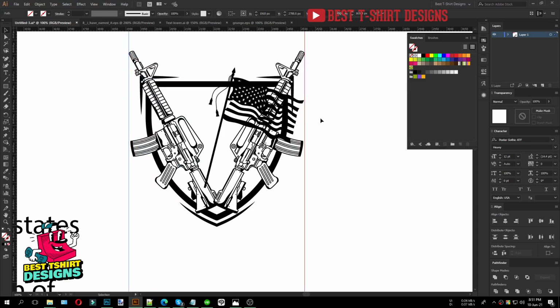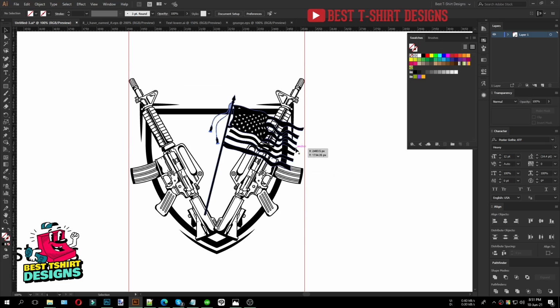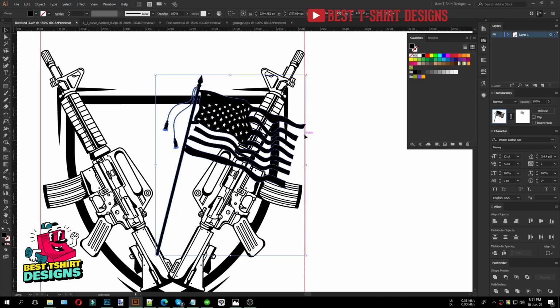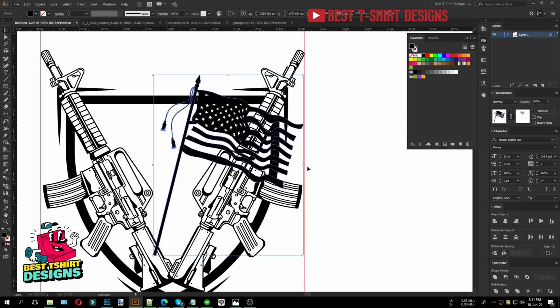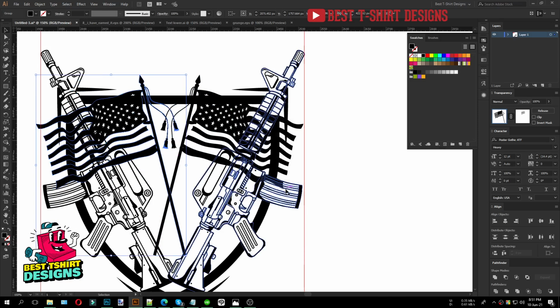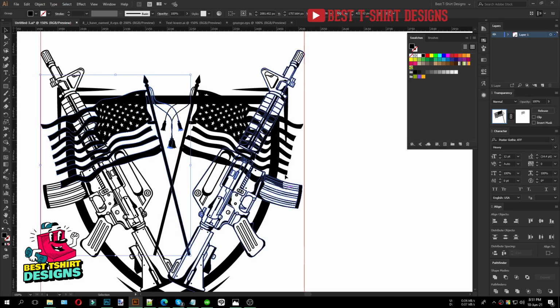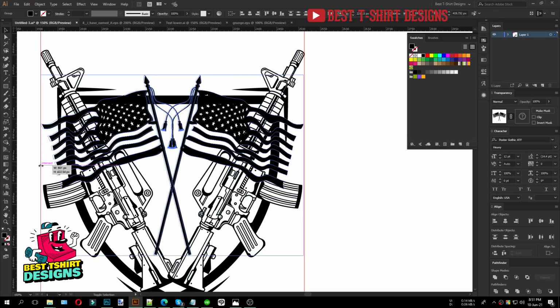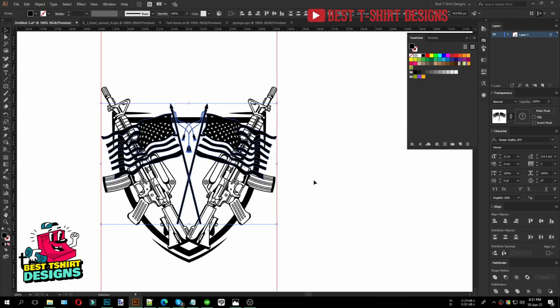I will not go outside of that area, and for that I am going to right click on the ruler and then lock guides, so that it will not move from its position. I want to make sure that my graphics are all inside this ruler area, then bring a copy here, reflect, Ctrl R, and then bring this inside the ruler area. I think that is fine, or I can simply manually fix it by aligning it with the ruler. Anyway, that much is good.